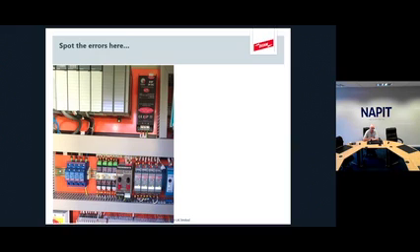So what the designer here has said is it's okay for the surge to go up and around that slotted trunking to get to the SPD, and then dump the fault down the earth wire attached to it back into the slotted trunking in there, where it's going to affect cabling and sensor equipment, which need not be affected. So that's not the right way to do it.